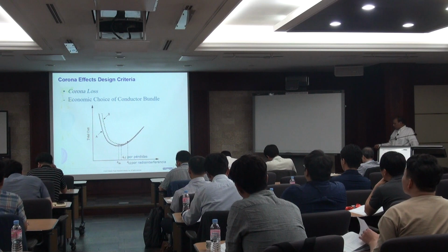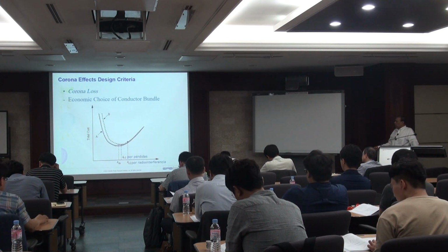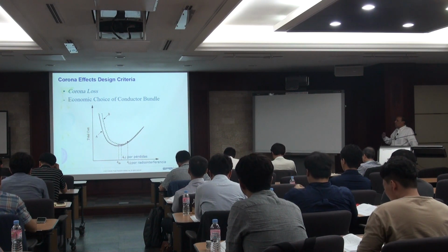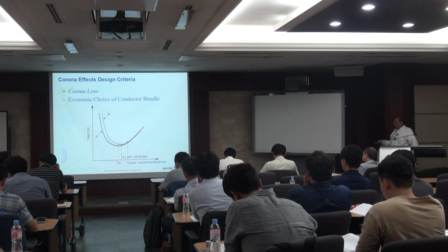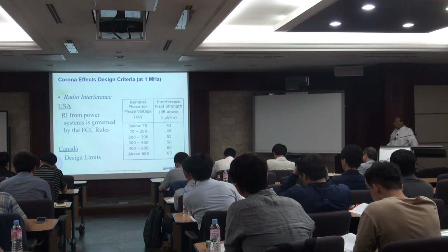Ultimately, the corona effects drive the line design criteria. You can have a low cost design of the conductor, but if that gives more corona loss, you don't want to go with that. You need to consider an optimal design, which has less corona loss also.